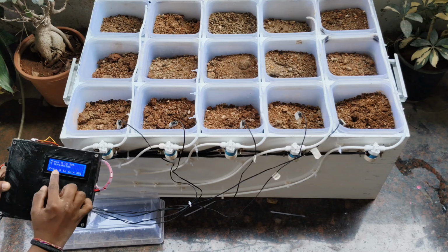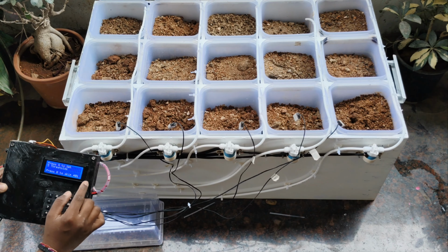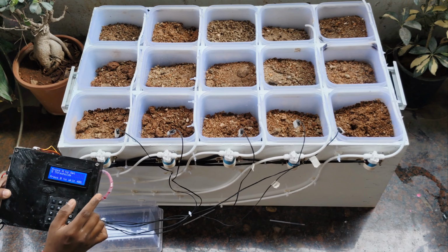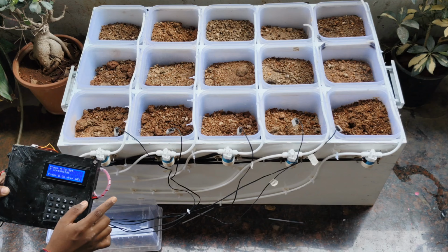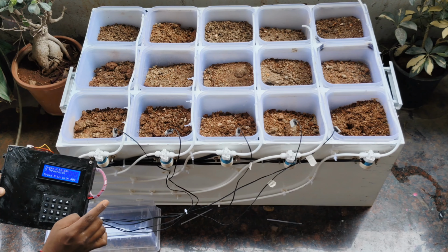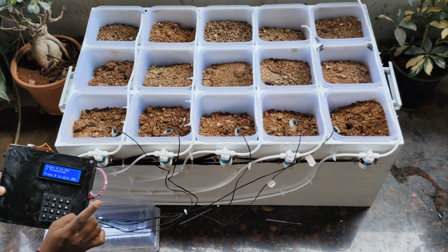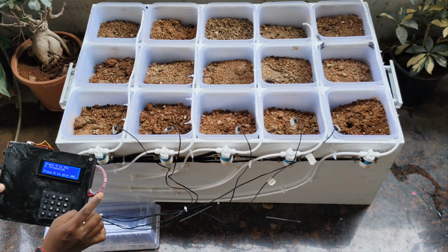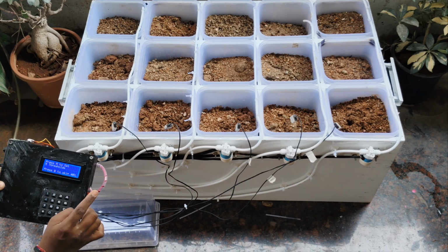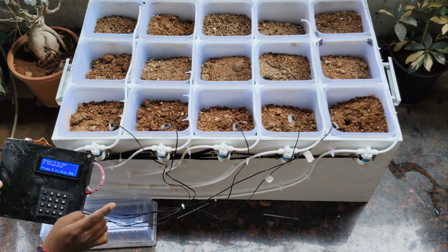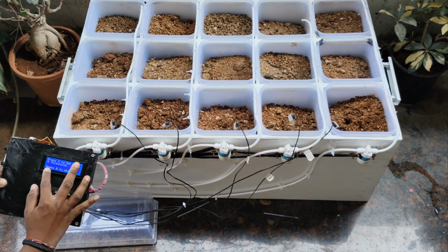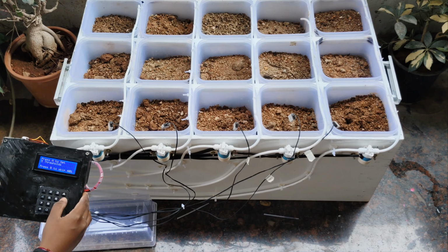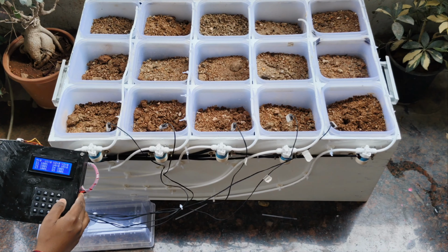It is asking me to save the threshold values. The threshold values are generally chosen according to the soil moisture content we need. If I want the complete system to be maintained at 40% soil moisture, I'll put the threshold as 40. If it goes below 40, it immediately turns on the valve, hence watering that chamber. So I'm putting all the values as 40, skipping everything to B so that all is set to 40.